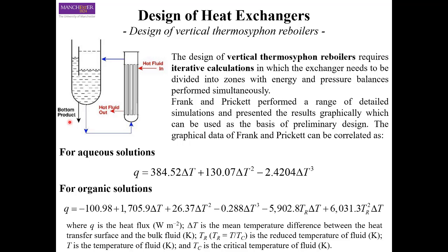When you are doing chemical engineering design, you have to be cautious regarding these correlations for boiling, especially because they are notoriously unreliable, unlike other heat transfer phenomena. Most of these equations that we showed today are only used for preliminary basic design of reboilers. If you want a more reliable design, then you have to use detailed simulations, but even then you should treat them with caution.